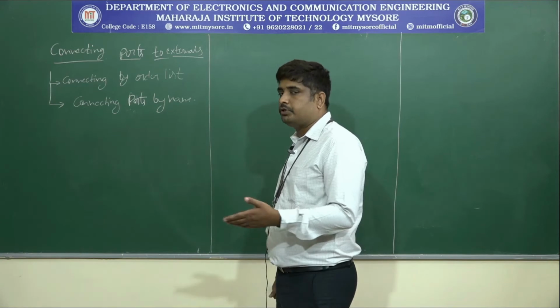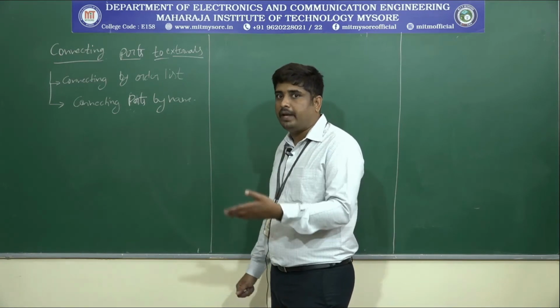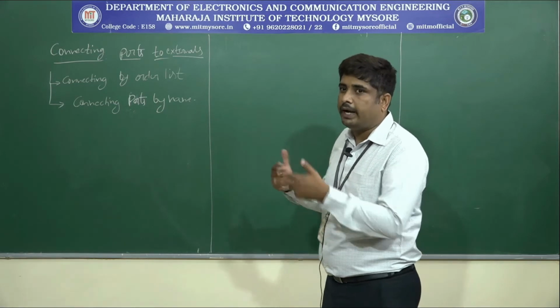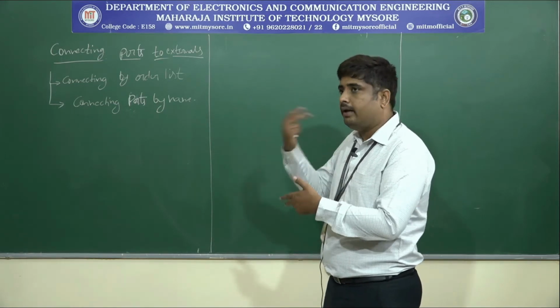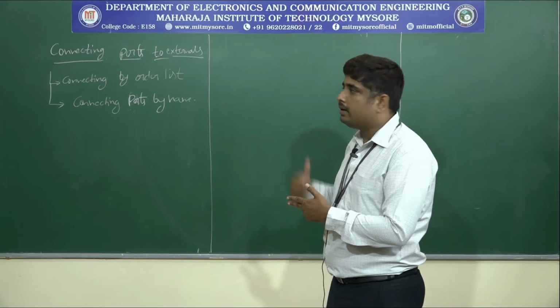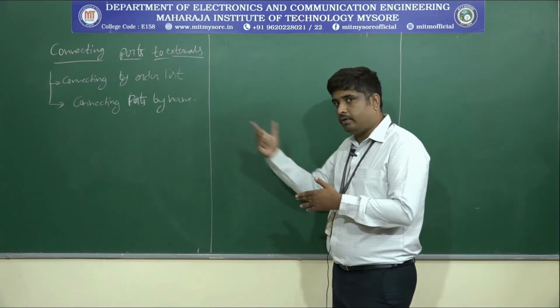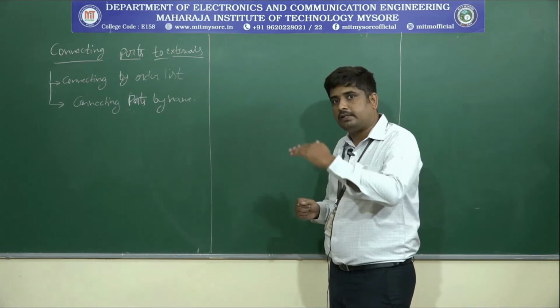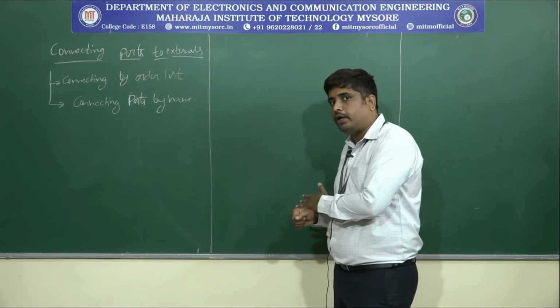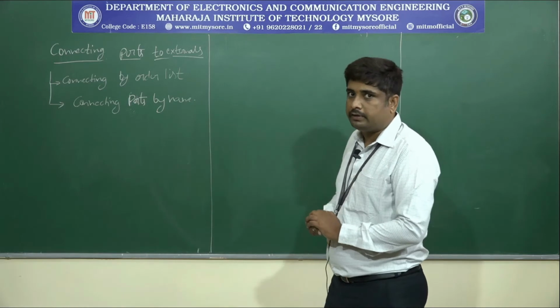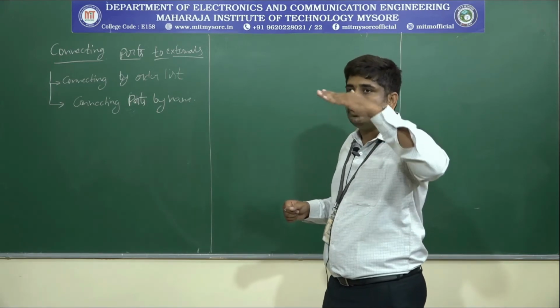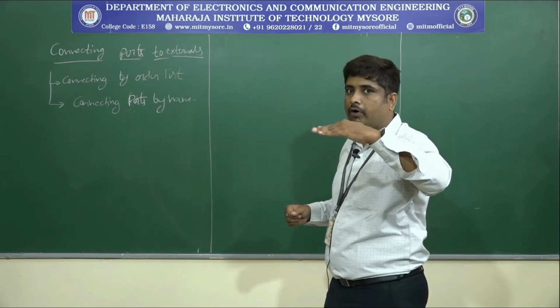It is one of the easiest methods for beginners. There are two representations, one is a top level block and another is a low level block. Let us take the example again of a full adder circuit, that is a 4-bit adder circuit. In the top level block there is a 4-bit adder, and in the bottom level there are 4 full adders. We name it top.